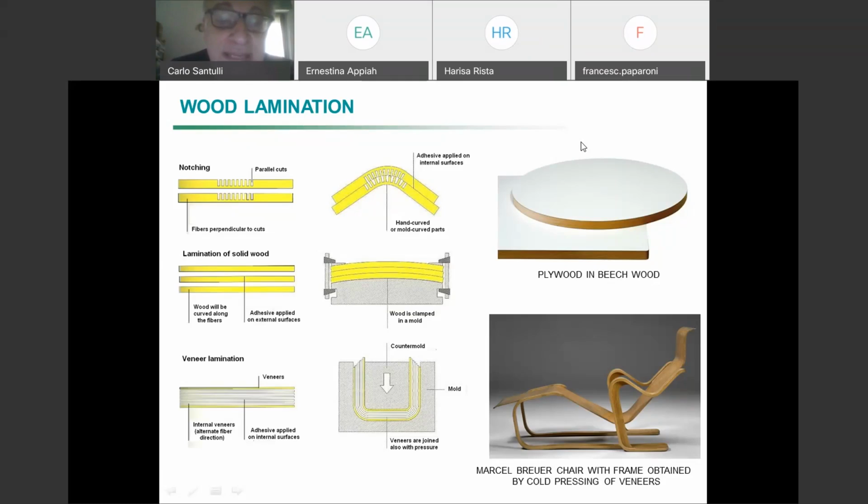You have these laminates, and you have already seen some slides the last time indicating the different types of laminates. You may have chipboards, basically with short random fibers. When I say random, I mean that the fibers are in whatever orientation. We are not able to say what they are. We assume they are roughly in all directions, in a 2D sense.